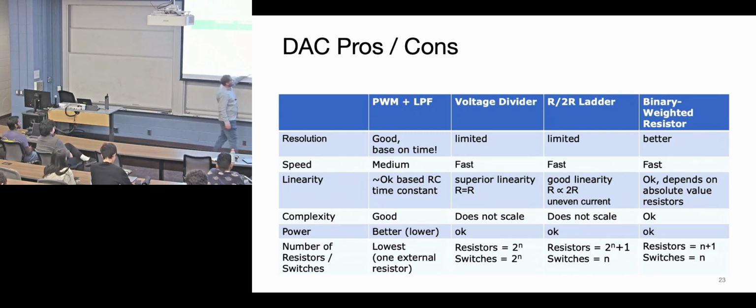And then we start thinking about the resistor counts and the switch counts. Switches, they're not bad, it's just they're a pain to make. They have to be biased, so there's some overhead for unintegrated circuit switches. So we say 2 to the N resistors and 2 to the N switches for that. So that's a challenge for the number of resistors and switches you need.